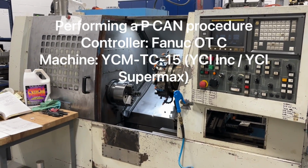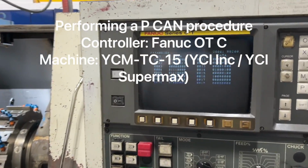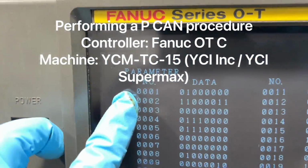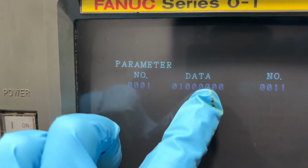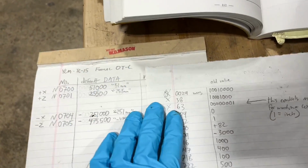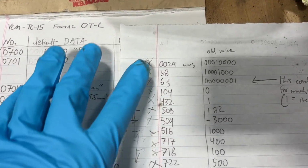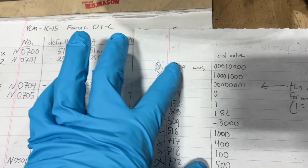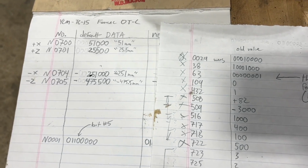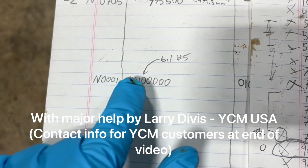The craziest thing that happened to me when I lost the parameters was staring right in front of me the entire time. Parameter number 1, as you can see, is 01000000. I never changed this one at all. It's the default parameter. When I got the memory restored, the batteries in and all that, these are all the ones I was messing around with, but number 1 I never wrote down because I never changed it. And it took me like 5 days to figure out this was the problem.